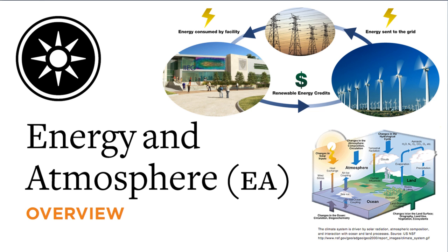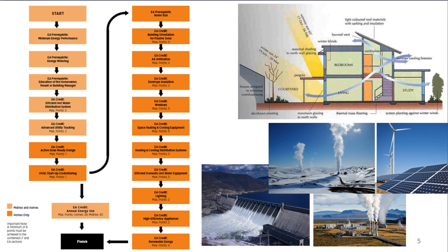Energy efficiency in a green building starts with a focus on design that reduces overall energy needs, such as building orientation and glazing selection, and the choice of climate-appropriate building materials. Strategies such as passive heating and cooling, natural ventilation, and high-efficiency HVAC systems partnered with smart controls further reduce a building's energy use. The generation of renewable energy on the project site or the purchase of green power allows portions of the remaining energy consumption to be met with non-fossil fuel energy, lowering the demand for traditional sources.